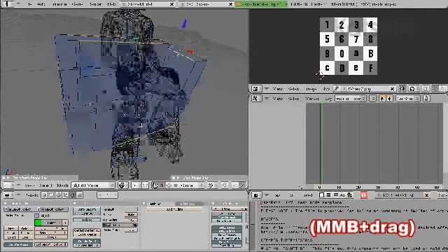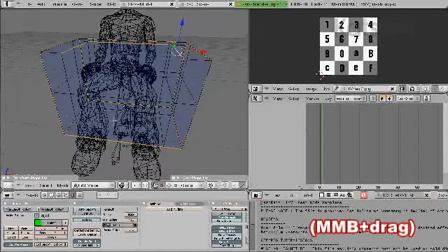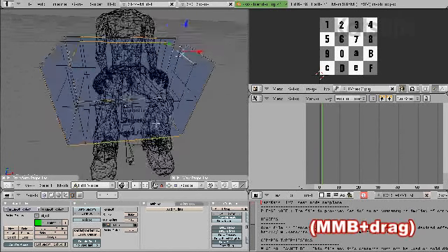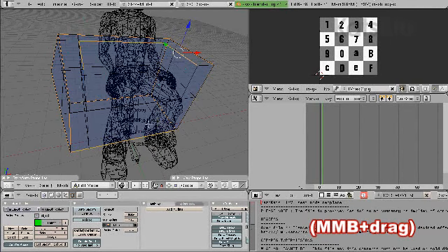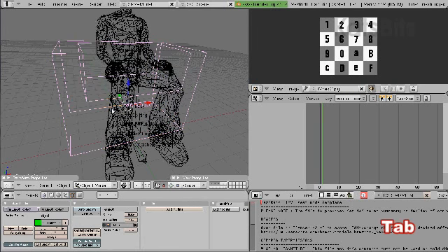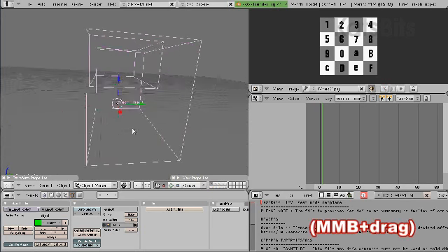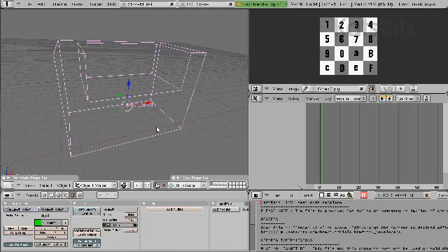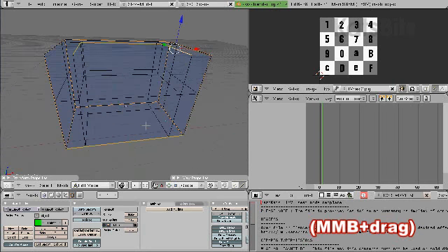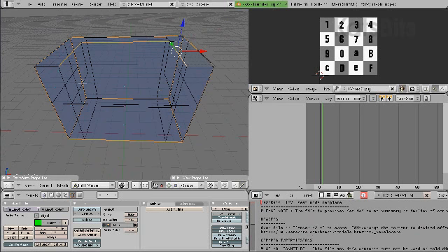Now we've got to a point where we need to make a decision as to how the inside of the mesh is unwrapped. Let's just make this a little bit easier to see by exiting edit mode, tab key, and left mouse clicking the layer that the chair mesh is in. That hides all the other objects and reveals just the chair, so we can press the tab key and continue unhindered. We've got to a point where we need to make a decision about how the inner surfaces of the chair are unwrapped.